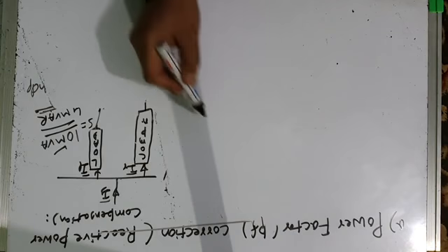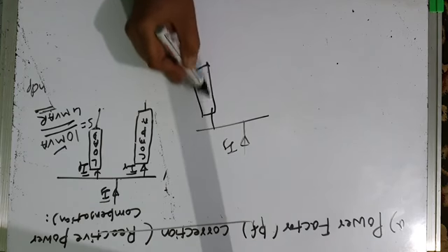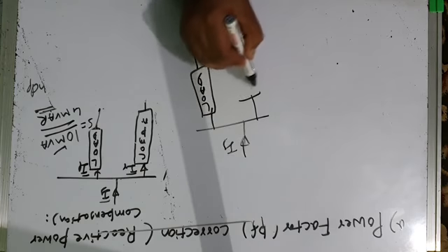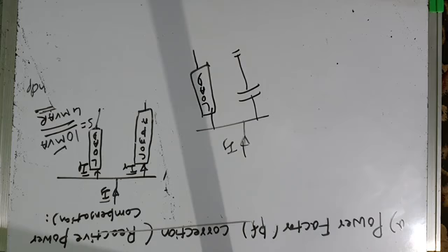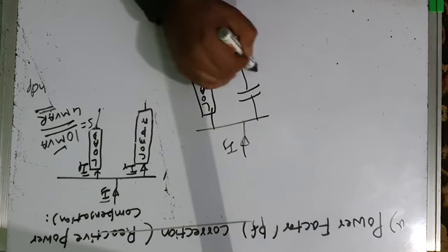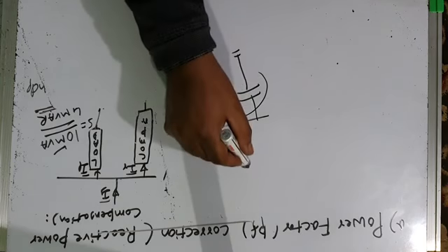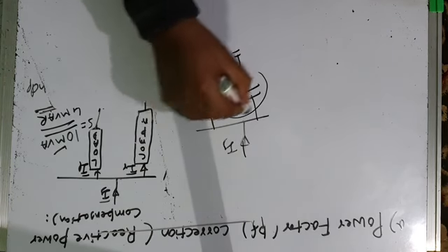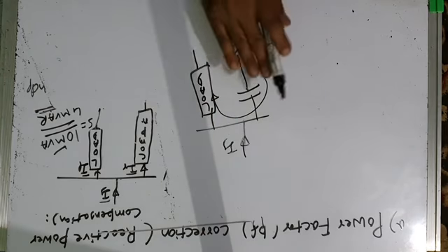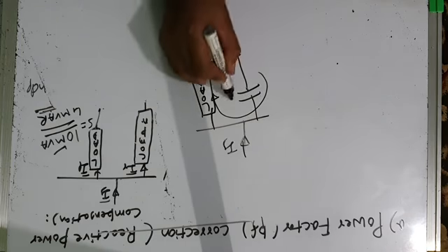This compensator generally आप substation में भी देखेंगे, अगर if this is your load and you want to provide the reactive power compensation of the load, what do? You connect a capacitor across the load. Because if load is demanding reactive current, inductive current, that capacitor generates the reactive current, and that reactive current, instead of coming from the source, is locally supplied by the shunt capacitor. This is the simplest way of having a shunt compensator across the load, or load compensator, capacitor.